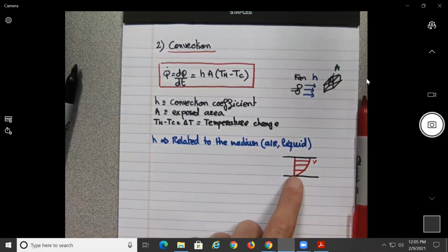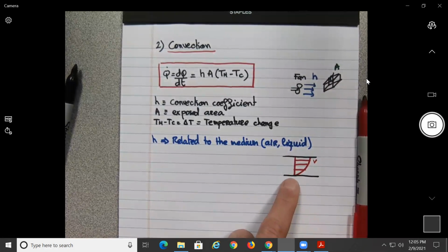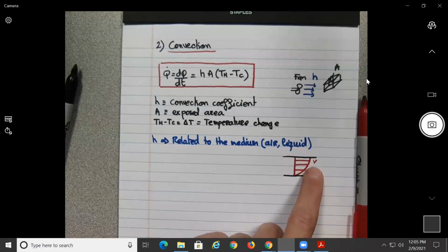No, that's what is called the velocity profile. So when the air touches your skin, because of friction, it is going to try to stop the velocity to zero, no? And the farther away you move from the skin, the higher the velocity will be until you get to the velocity of the flow. So also the velocity will depend on the quality of your skin, maybe on the color of your skin or the type of skin that you have. The h will be different, okay?